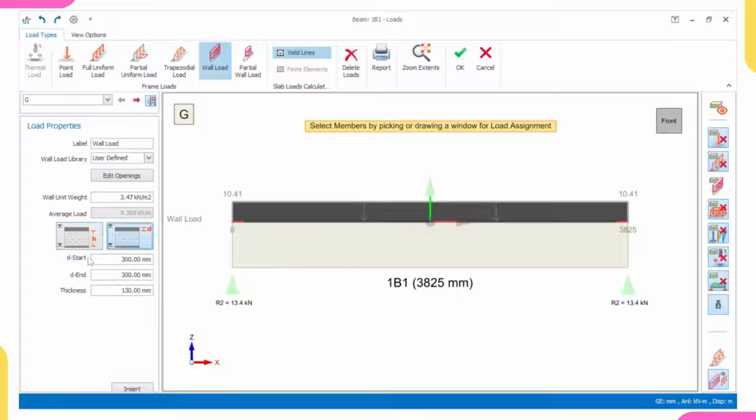If you see, that's our drop down beam, this D. Look at it, our drop down beam is 300, while the remaining part from the drop down beam to the floor is 2,700. If you do 2,700 plus 300, you have 3,000. So what is our block thickness? It's 225. That's the block thickness we are using.